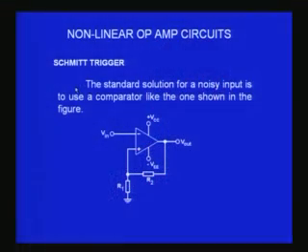So what we do is increase the hysteresis, the levels at which the voltage transition occurs at the output. The corresponding circuit I have shown here. From the output I have connected a potential divider R2 and R1, and I have taken the potential divided output to the plus input of the op amp.